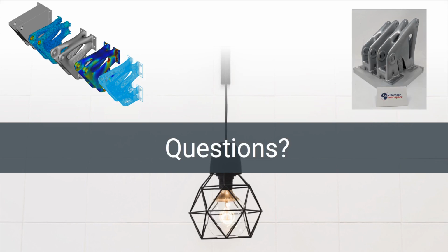There's one on whether smoothing is first necessary before additional downstream work. The only absolute requirement is that you convert it into implicit. There is a generalized function call in the software to smooth that implicit. So it's not required, but depending on your mesh size and your topology optimization, you could get a boundary mesh that you may want to smooth. Technically it's not required, but it is generally useful.